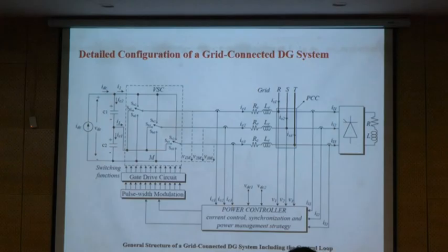The importance of this topology is that when we split the DC voltage, assuming that we have a 2-level and the voltage is 6,000 VDC, then VDC goes over the transistor, okay? So 6,000 drops over each transistor. But when we go 3-level, this 6,000 is divided by 2.